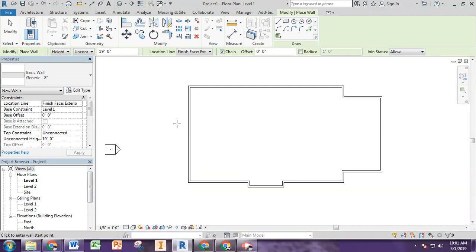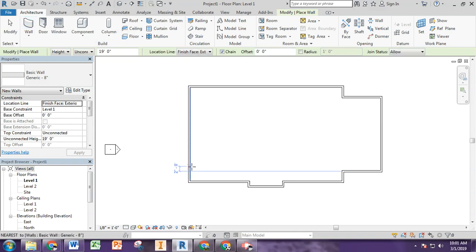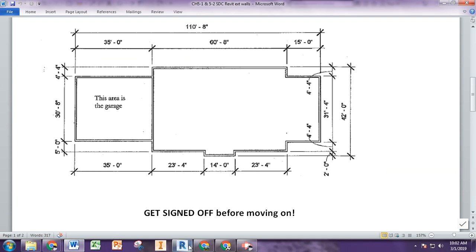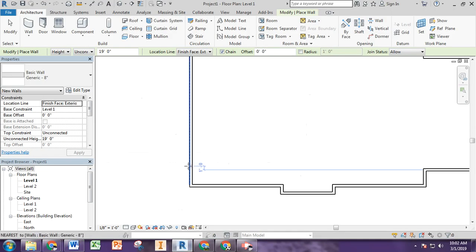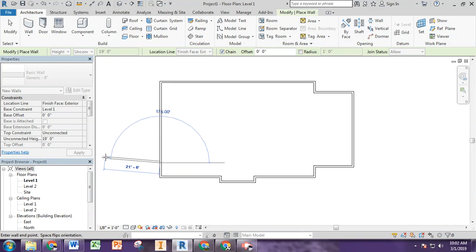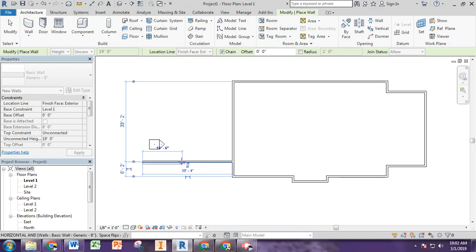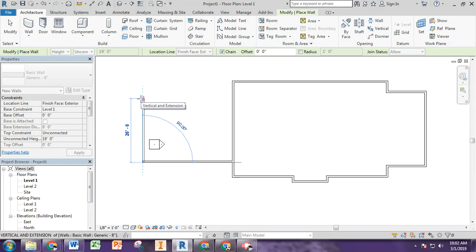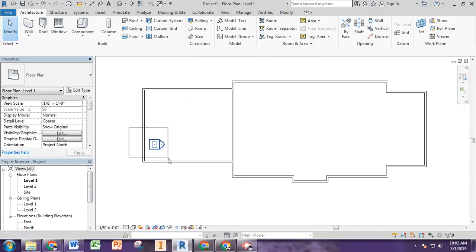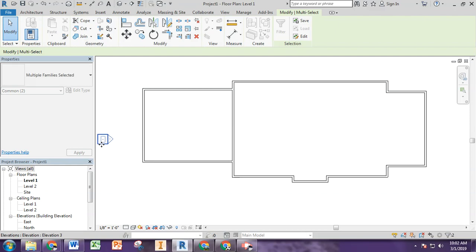And there you go. Now to draw your garage wall, you come in and click again, and imagine we're going clockwise, so we want to start in this bottom view. Here's your garage wall, it's 5 feet up. You can zoom in so that you know that you're 5 feet, although it's not going to toggle to that dimension, unfortunately. So I'm just going to start drawing, and we'll dimension it later. If we captured that little triangular shape, we can move that later. To move that, you can just draw a box from the left to the right around it and drag it out there.